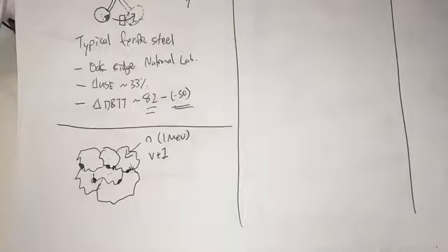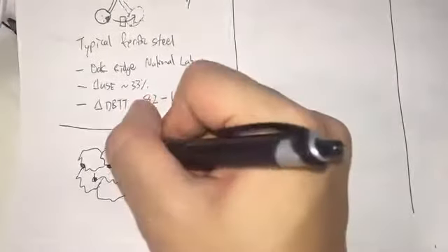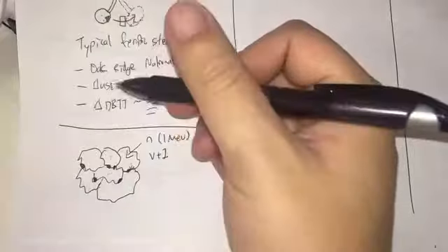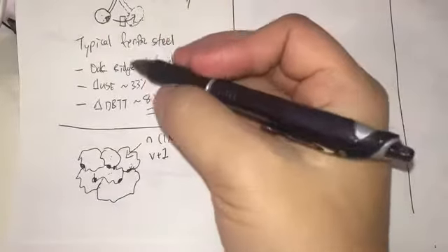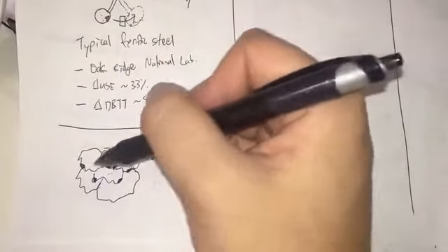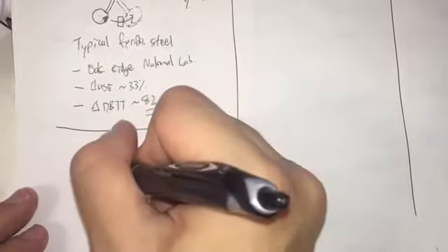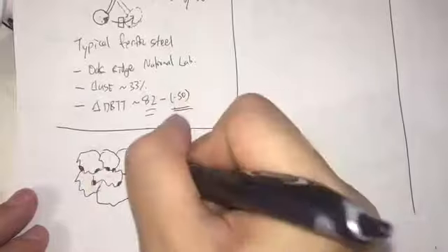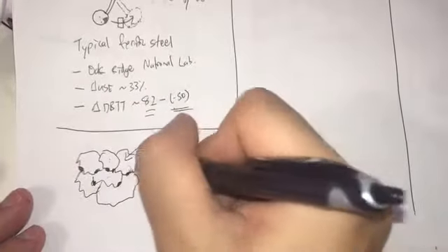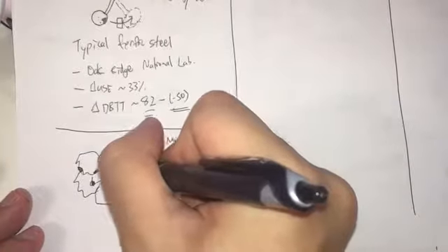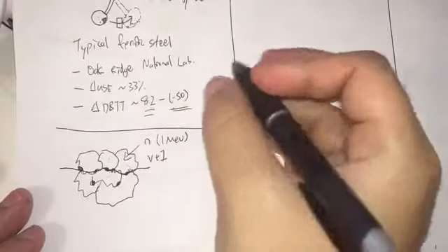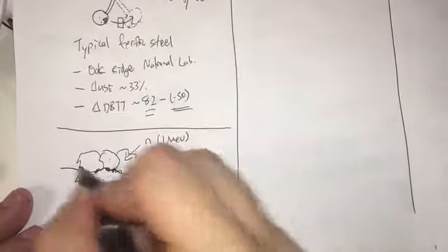Within each crystal, you may have a ductile behavior, but on the whole, because the attractive force between grains drops, we can have intergranular fracture. This means the fracture doesn't occur within the grain, but rather between grains.